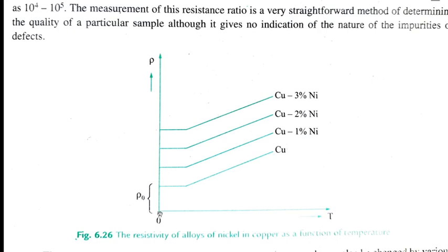Here it does not mean that we have not added any particular single impurity, because some dislocation of atoms is also possible, or maybe during the formation of a crystalline material certain defects arise, which is always considered to be independent of temperature. So, residual resistivity could be strongly caused by the impurity, but it could also be caused by some permanent impurity or permanent dislocations, and that is why pure Cu also has a certain resistivity.